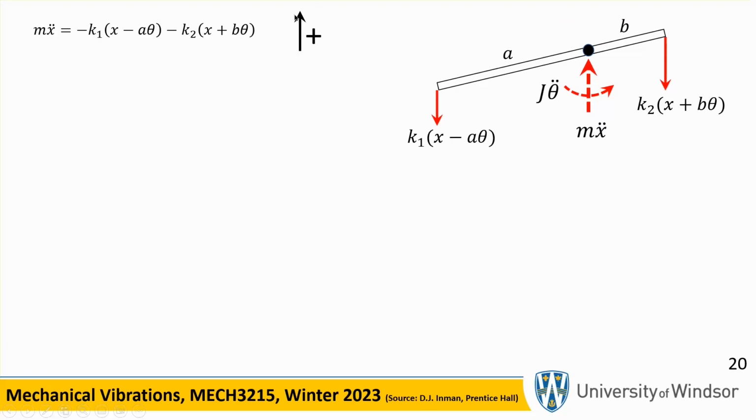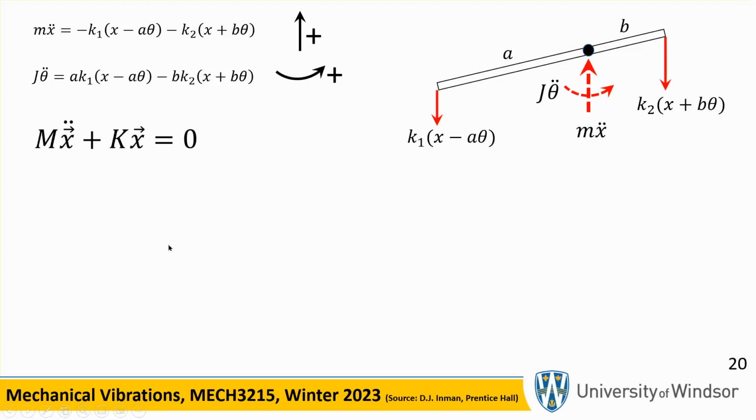Okay, this is vertical force in the upward direction, mass times acceleration, forces. We take the moment about this point patiently, respecting the direction of rotation, positive counterclockwise according to this drawing. And so this has a negative contribution to the moment, and this has a positive contribution to the moment. Okay, it looks like that, the mother of all equations. Your x is vertical displacement and counterclockwise rotation. It's not always all displacement, all translation, sometimes mixed. In this model it is a mix.